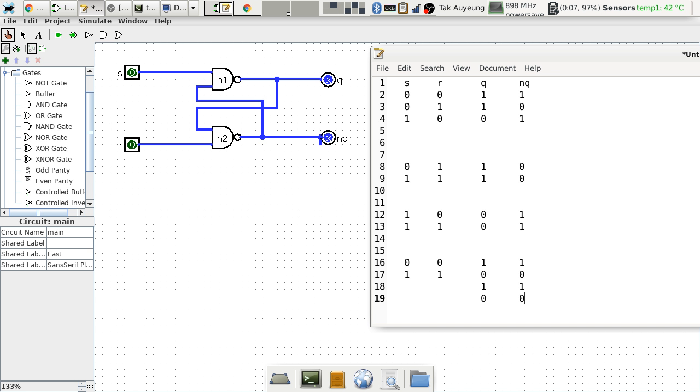And it will never end. In other words, we enter a state of oscillation. The circuit will now oscillate, and the half period of the oscillation is going to be the propagational delay of a gate. If the propagational delay of a gate is 2 nanoseconds, then the full cycle is going to be 4 nanoseconds. But every 2 nanoseconds, you will see a transition.